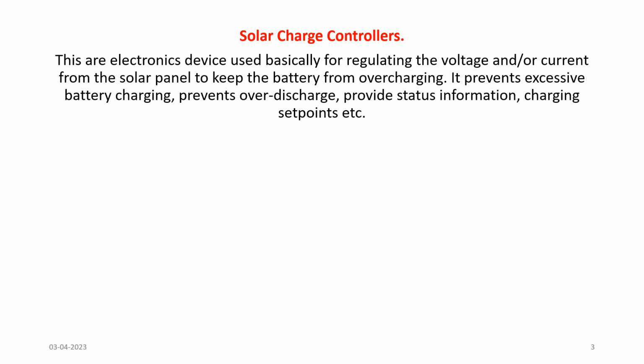As we know that depending on your configurations too, we have something to charge your battery, and you know that our battery is the storage. Used for energy backup, used as energy storage. So charge controller, basically, some call them boost converters, they are buck boost converters. So they are converters too. You getting it? Because it's a DC to DC converter.